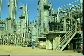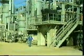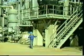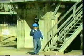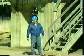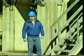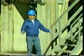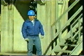Oil and gas are produced together, and the gas pressure after separation is often too low to meet the processing requirements of a large plant like this one. Gas pressure also needs to be at levels high enough for proper handling through pipeline sales facilities, gas lift, and injection purposes. So compressors are used to raise the gas pressure and meet these high pressure requirements.